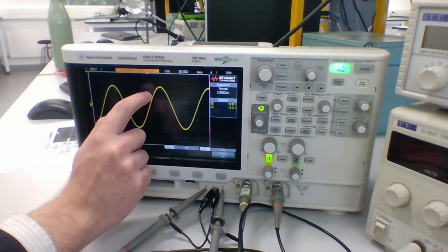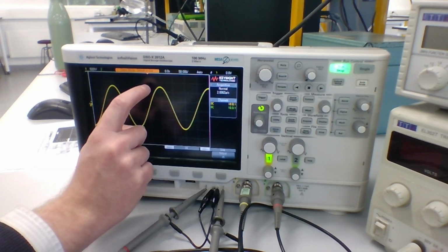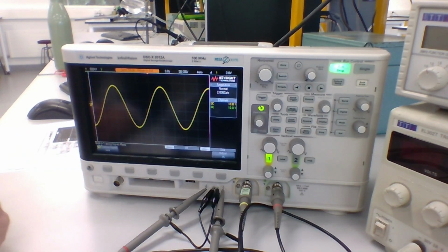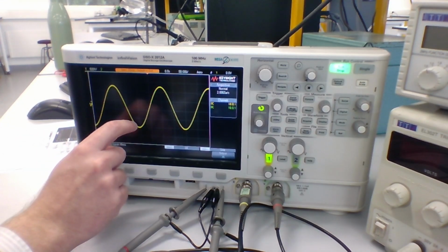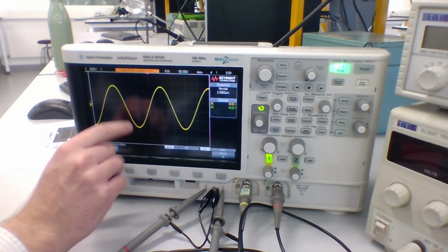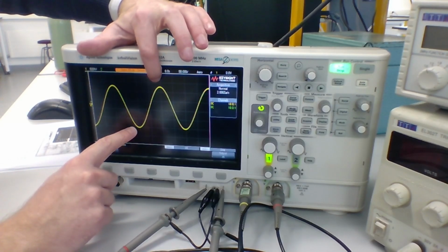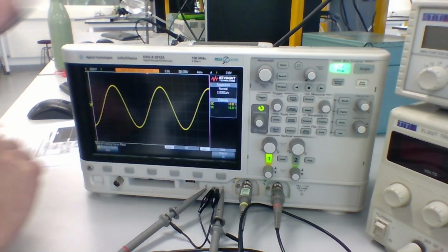And I can use the subdivision there and say, well, I know that in this case each of those is going to be 100 millivolts, that's broken up into 5 intervals. So have a go at doing that to estimate what the peak-to-peak voltage of this waveform is. Remembering that peak-to-peak means literally the difference between each of these peaks, or the peak and the trough here.